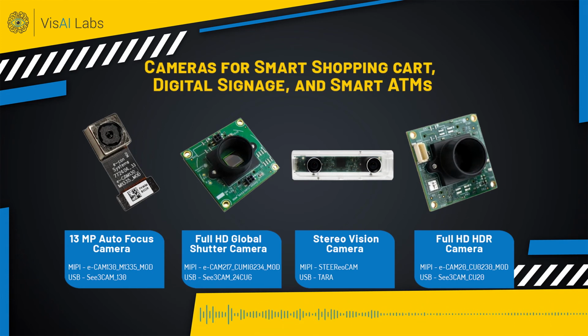Let's assume you want to capture images in a shopping cart. If you want to capture it while it is in motion, you would need a global shutter camera. A rolling shutter camera will create rolling shutter artifacts that might create problems for your algorithm to detect the objects rightly. It could be like a fruit, or it could be a barcode. In both cases, if it is a moving object, global shutter would be a better choice.